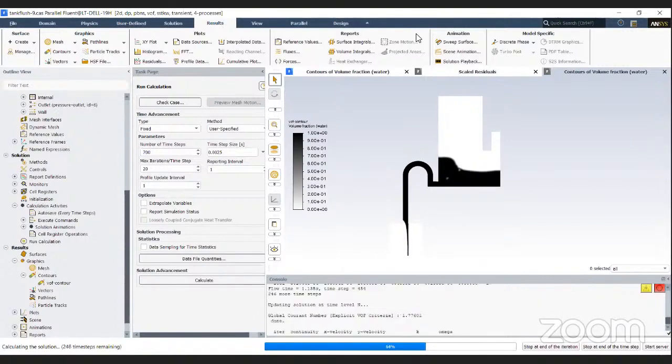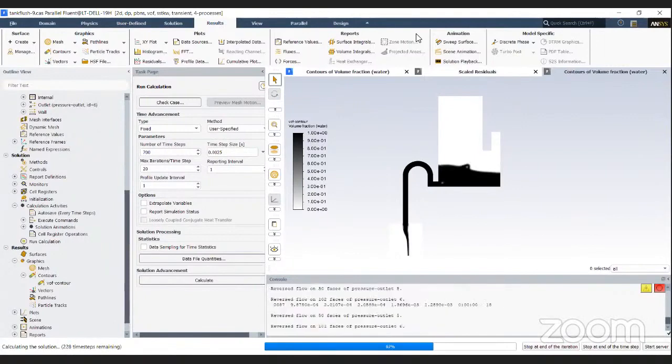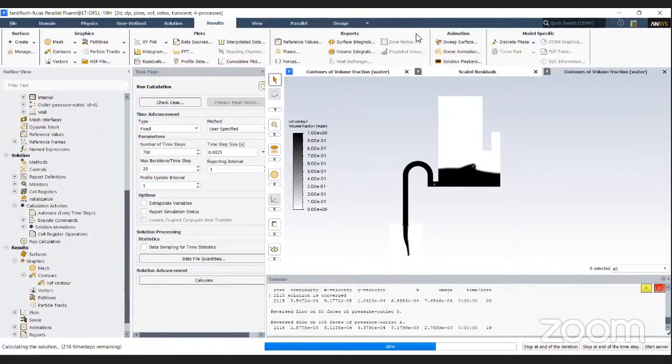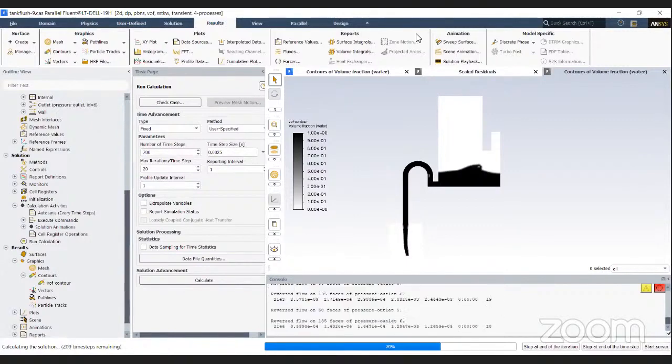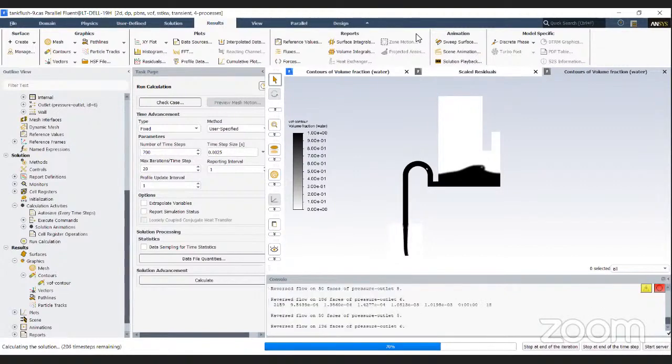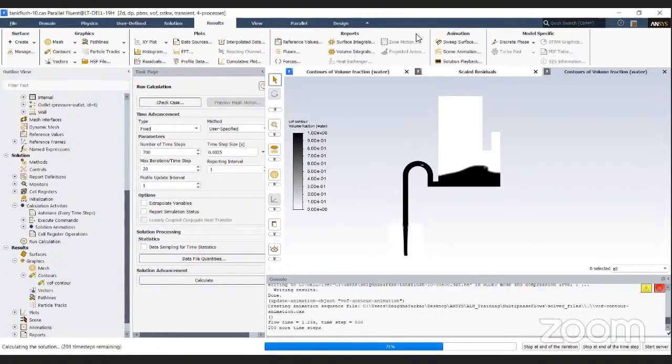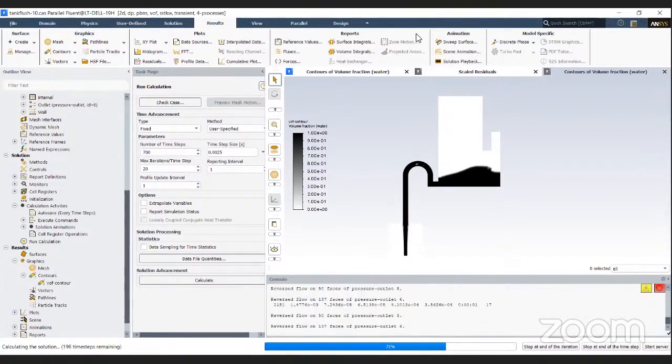But sometimes approximations also work. For example, even though VOF is more suited for a type of simulation wherein you're trying to capture the boundary, if you don't think that boundary is that important, you could go ahead and just use VOF as a blanket model for something of that sort, wherein you just need to make sure that the computational grid is small enough or comparable enough to the boundary of those bubbles that you're talking about. So it'll definitely take care of the free surface flow.